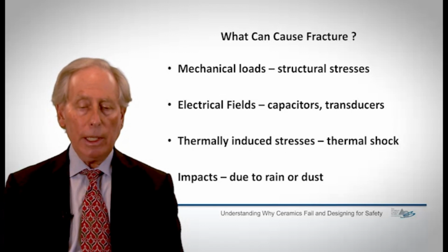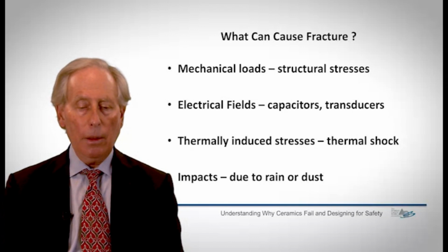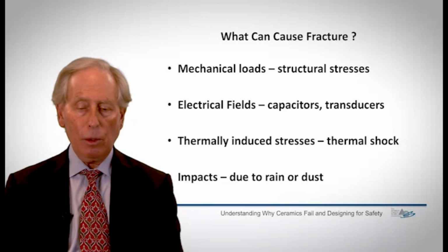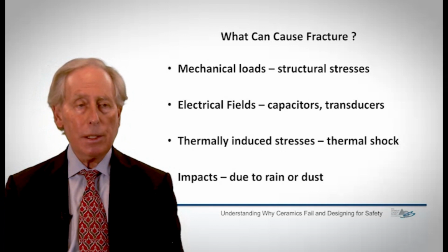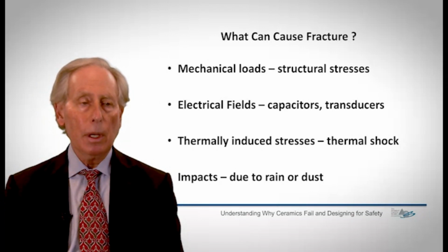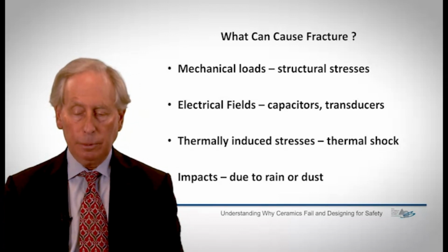But interestingly enough, electrical fields can produce stresses in materials, in capacitors and transducers. Thermally induced stresses due to temperature differentials. I mentioned thermal shock. I'll talk more about that later. And you might recognize that impact due to rain or dust on a material can produce damage, which under fairly low stresses can also produce failure.